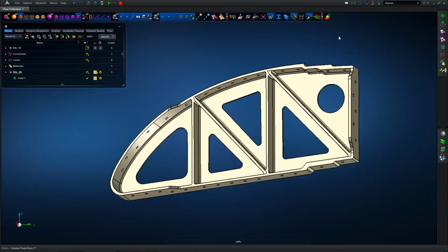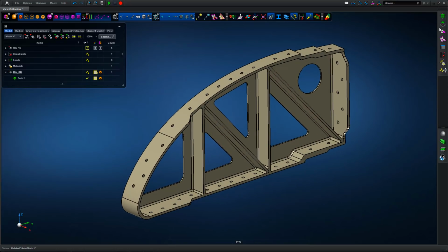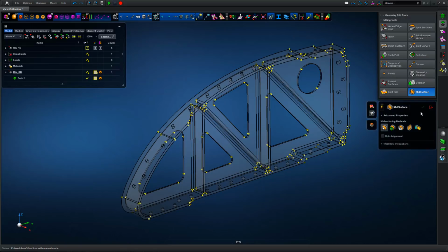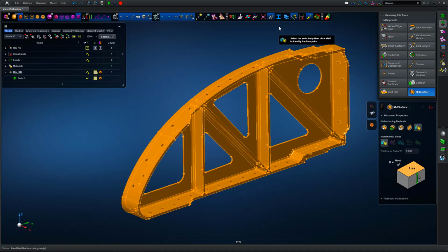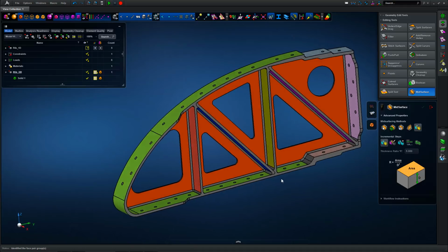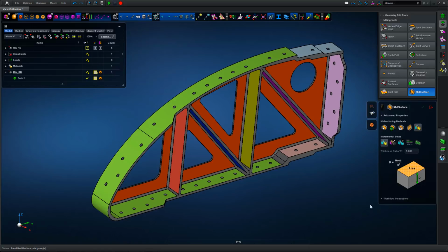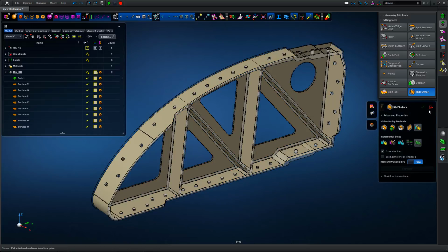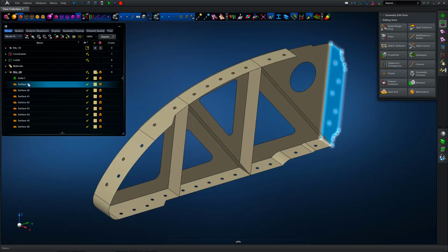So second approach. Now this is the 2D representation that will be used for a joint load definition or stability assessment for this type of structure. So again, exactly the same CAD geometry, similar technique to start off with, in the fact that we're going to use the incremental mid-surface tool to pick out paired surfaces, or paired faces I should say, to generate the mid-surfaces. And again, happy with those pairs, select the pairs to create the underlying parent geometry, and we can turn the CAD off and show the surfaces as required.